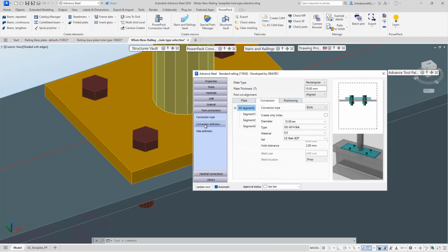I think another thing to point out to everyone is this works also if you've got a railing that isn't actually connected to anything at all. So maybe it's just drawn using the line option or point option that we have. So you don't need a supporting body for it, whether it be a piece of concrete or a steel beam in this instance. So in that case, you may choose not to provide the fixings at all and just provide a hole. Now previously when we did this, we were limited to round holes.